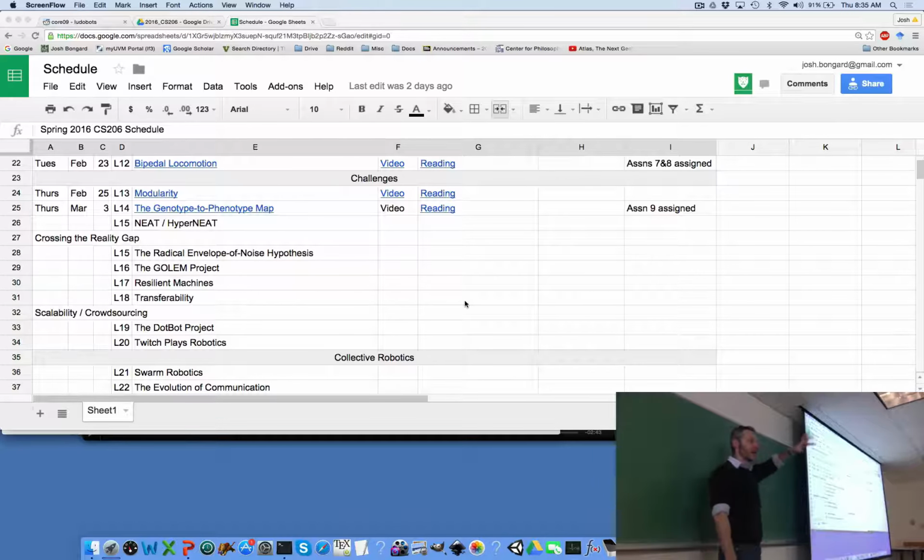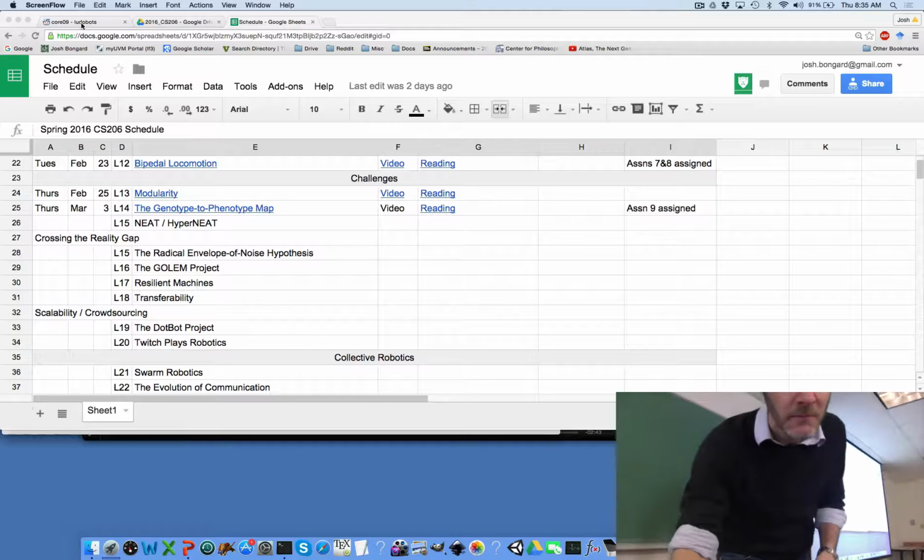Your robot will dance around for 1,000 iterations through the client move and display function. It'll move around, and at the end, you're going to measure what about the robot? The distance from the origin, right? So we're going to get one number, which is the distance or the fitness. We'll send that back to the hill climber here. The hill climber will create a new 4 by 8 weight matrix, send that across, get the fitness back, and around you go. Make sense? Okay, so let's just have a very quick look at assignment 9.